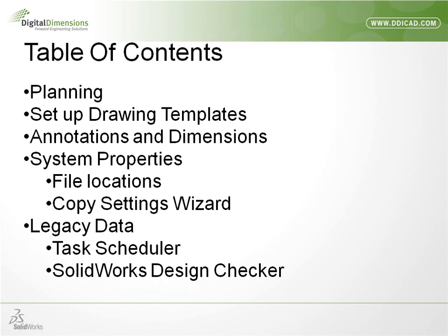When I say system properties, I'm referring to each workstation. Each workstation has its unique settings, and if everybody in your work group is going to produce the same drawings, then you want to make sure that their workstation settings are the same. One item that comes to mind specifically is the file locations for your templates. There is a utility that will allow us to make sure that all of our workstations match. This is referred to as the copy settings wizard.